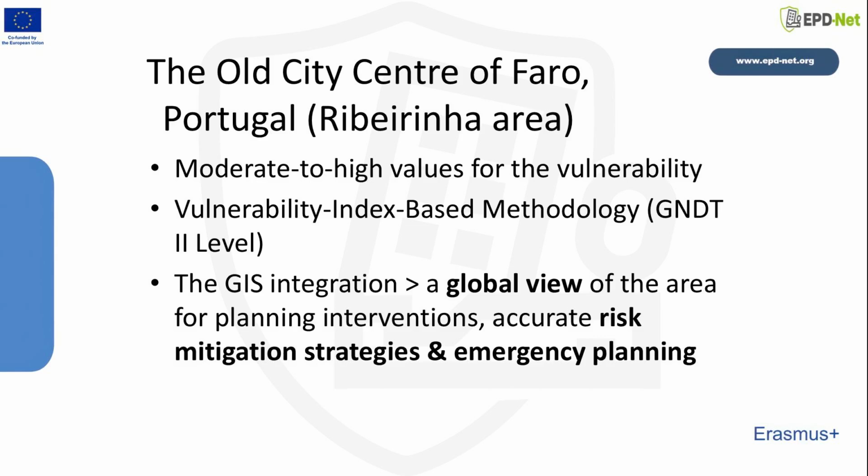Similar studies have been carried out for the old city centers of Seixal and Coimbra, Portugal. The core framework used is the Vulnerability Index-based methodology, classified as a hybrid technique. This approach calculates a Vulnerability Index score, IV, for each building based on 14 weighted parameters, P1 to P14, that evaluate aspects like the type of resisting system, number of floors, and conservation status.